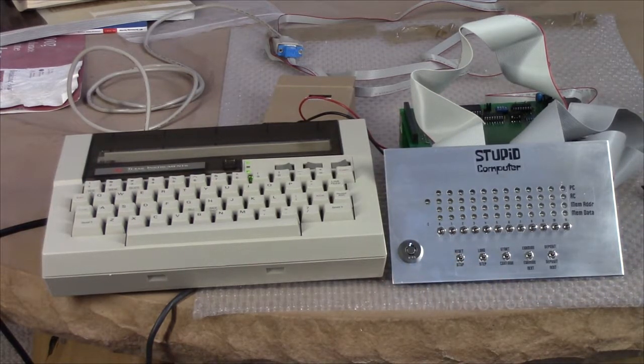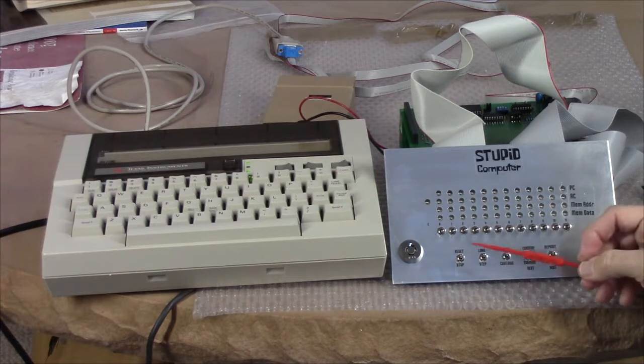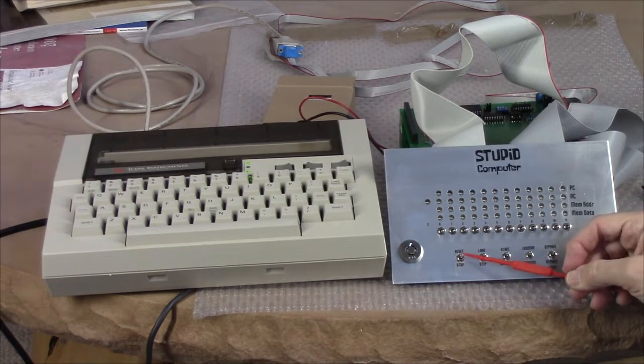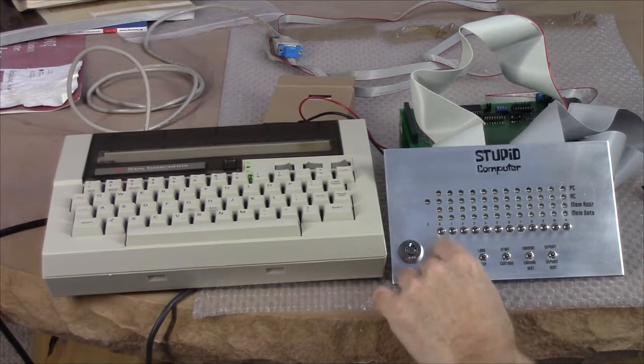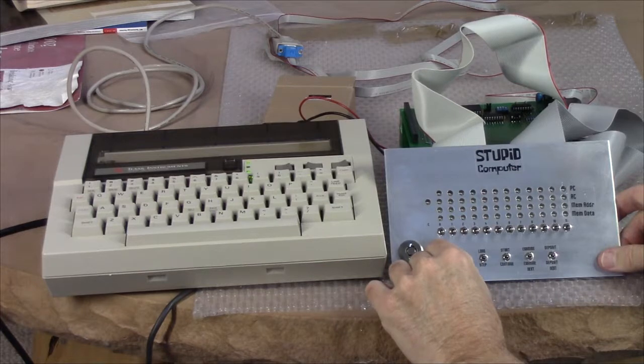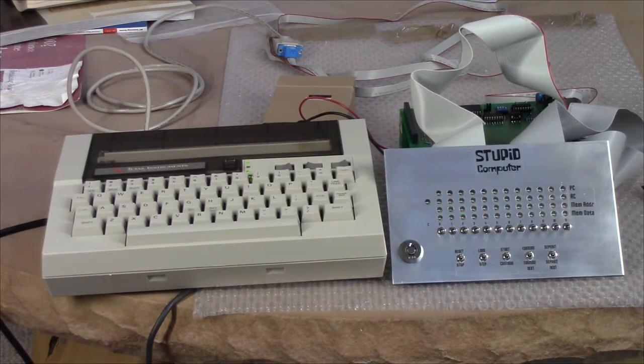Now, how do you tell a power on reset from a switch reset? Because to the computer, it just sees the reset line pulled low. Well, I played a little trick there. You'll notice that the stop switch and reset switch are on the same physical switch, okay? So it is impossible to press stop when you press reset. And so I used that to my advantage.